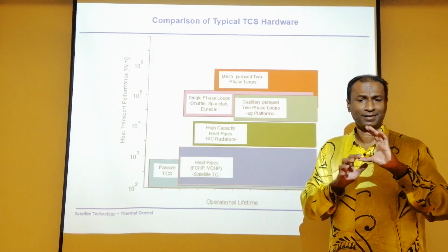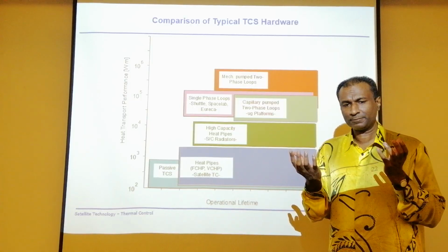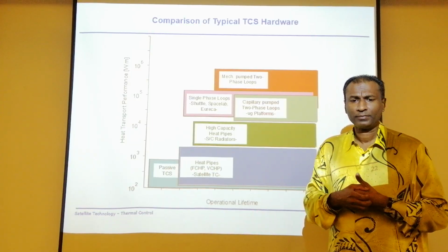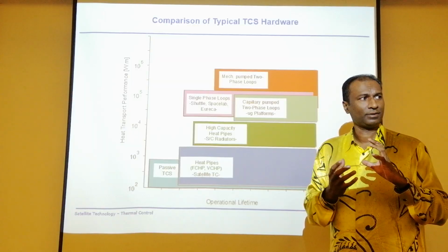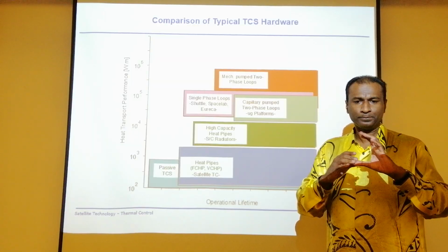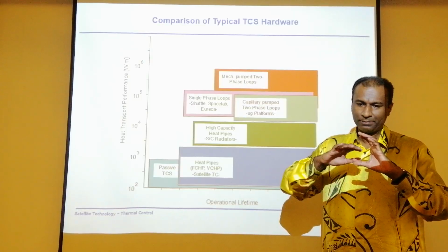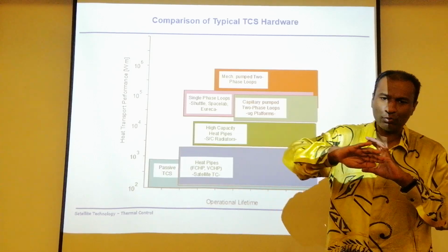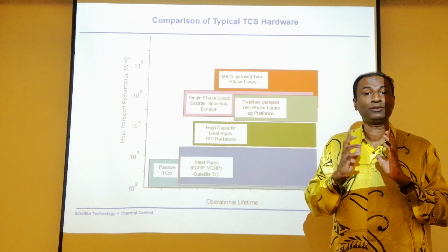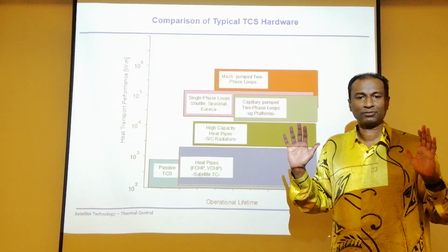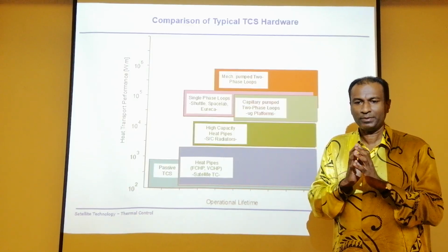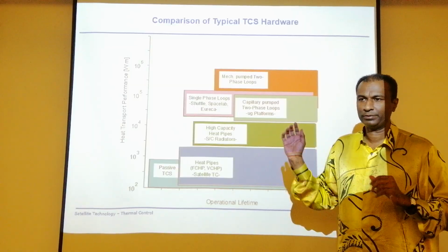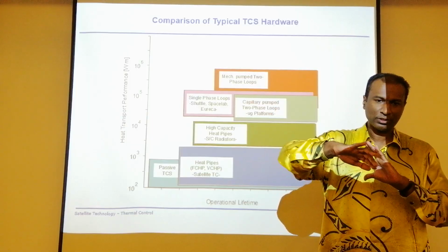What is the capillary effect? When the particular fluid, maybe water or ammonia, is heated up, it will evaporate, and the evaporation happens towards the wall, retracted, and then the flow is created. That's how it works. But you need to have the heat. Without the heat, nothing. There's no change of phase. Liquid will just stay liquid. The evaporation takes place in a place called the evaporator that we will see later. So then it goes on to flow.